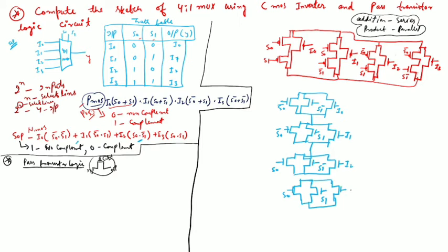So here this is the I3, connected in the middle from the above circuit. This will connect to ground, and this will connect to the middle of the pull up network above. The one below is the pull down network, and from this we take the output Y.